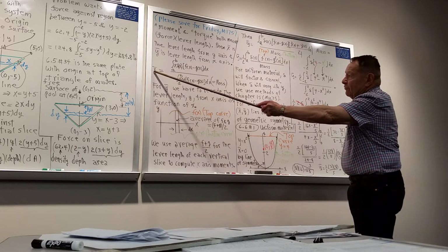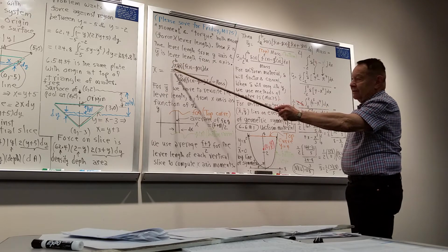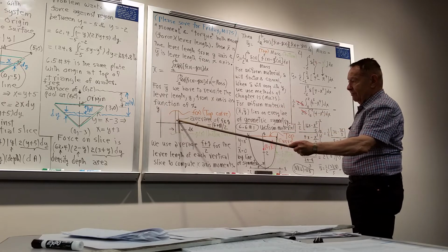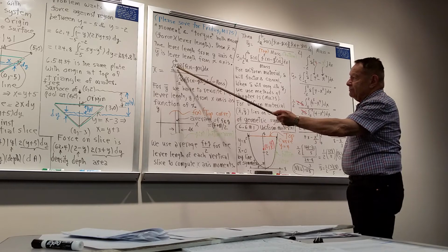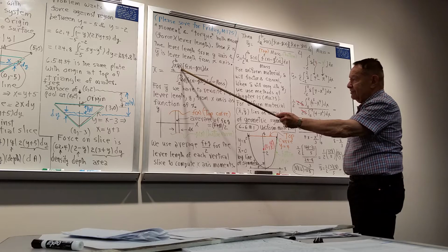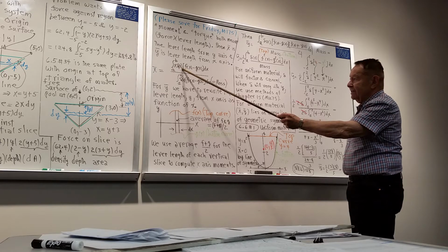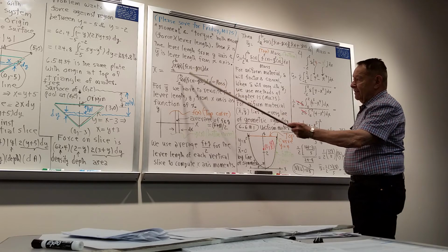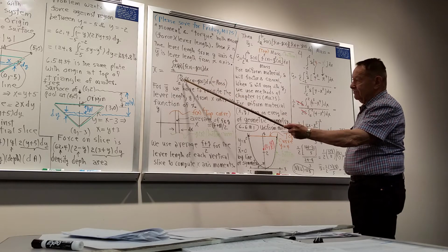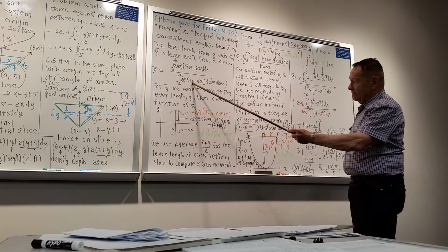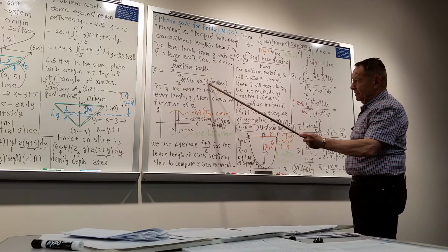So the x bar formula is your integral, your leverage, measured over from the y-axis, times your density, if it's variable and is a function of x so that our problems can handle it, times our differential area. And we divide by our mass, which is the variable density times the differential area.